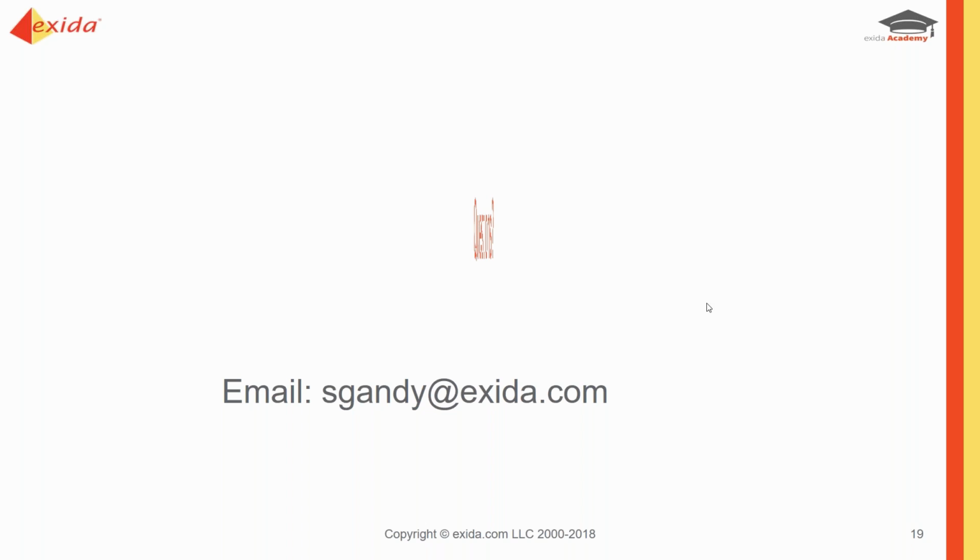Again, the standard says periodic. It doesn't say when. And most of the time you could use the 5-year window between doing PHAs, because if you haven't had any incidences, but you've been doing your proof testing, you've been doing your maintenance, you've been recording data, then that's a useful period of time, because you can use the assessment to feed into the PHA team, just to make sure that there have been no changes, or if things have been better than you thought, first of all, then you can maybe modify.